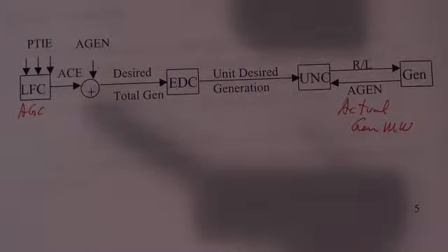One is to send a set point that says, give me that many megawatts, and the control system at the generator will run it up and down to give you that much. Or you can have this whole AGC system say raise, raise, raise, and the generator is supposed to come up a little each time you tell it to raise. And then if the frequency starts turning the other way, you say lower. So it might be raise, raise, lower, raise, raise, lower.